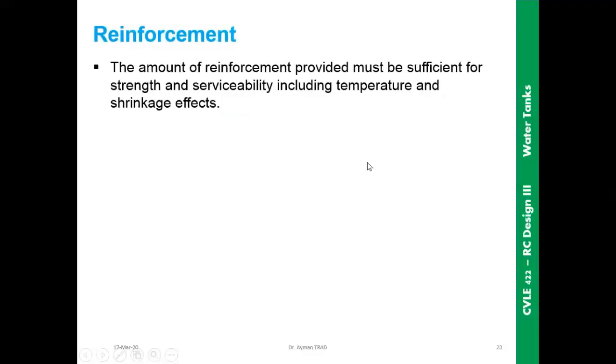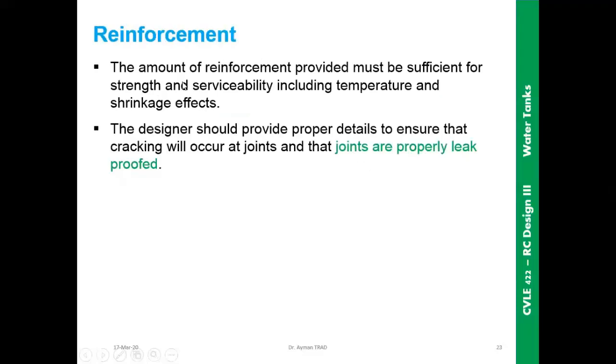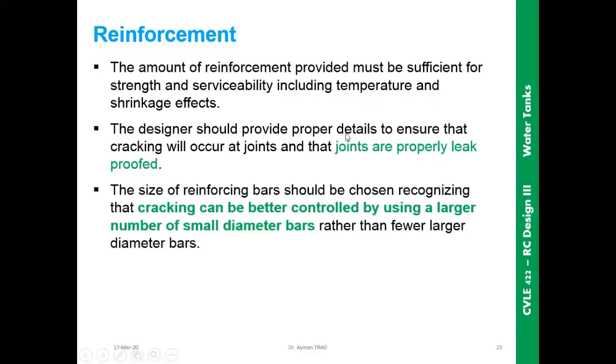About the reinforcement, of course we need reinforcement more than the minimum, to ensure reduction of movement and deformation due to the shrinkage and temperature effect. We make sure that the joints are well waterproofed by the water stops. So I need to make sure of the details of reinforcement near the joints.